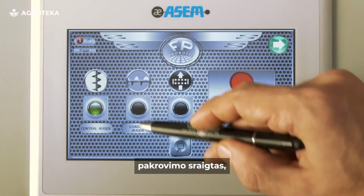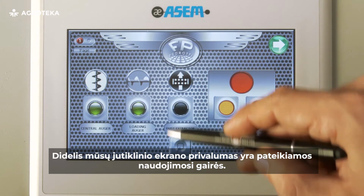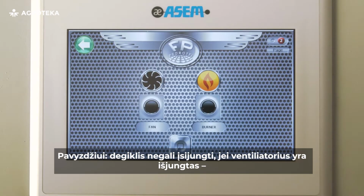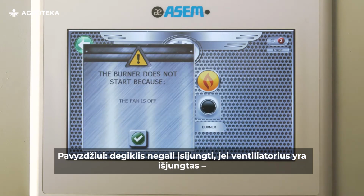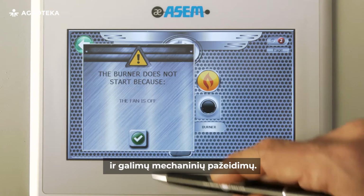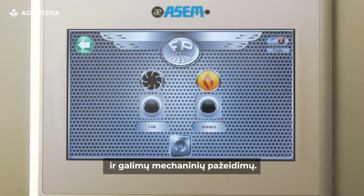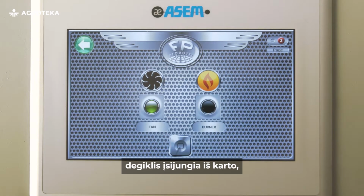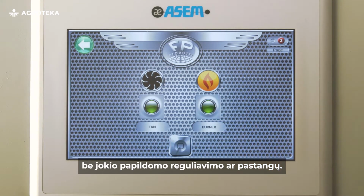Central auger, loading auger, dust extractor. A great advantage that our touchscreen offers are the guidelines provided. As an example, the burner cannot start if the fan is off, to avoid thermal deformation and the consequent mechanical breakages. Following the correct procedure instead, the burner will start immediately without any efforts or regulations needed.